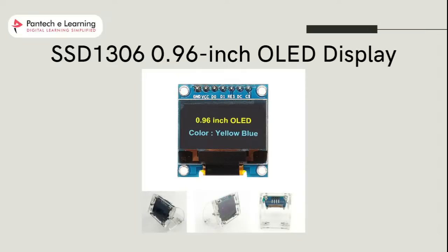The main component of all different types of OLED display is the SSD1306 controller, which uses either I2C or SPI protocol to communicate with the microcontroller. Mine is an I2C based OLED. The OLED performs faster in SPI communication, but it is popular with I2C communication because of the lower number of pins. You only need 4 pins. OLED displays can vary in size, color and shape, but they are primarily programmed in a similar way.